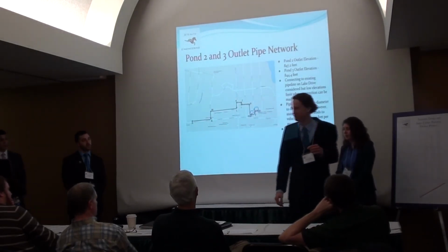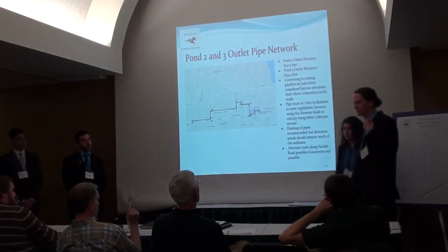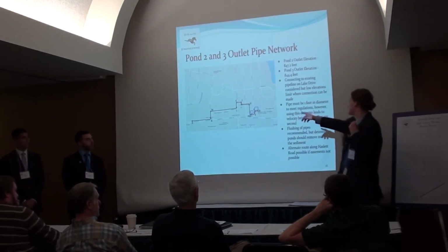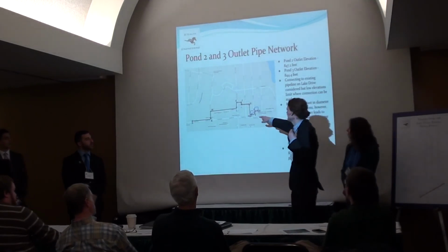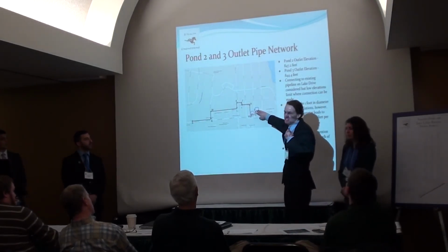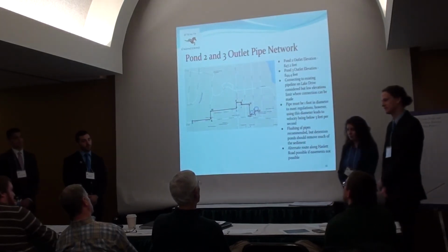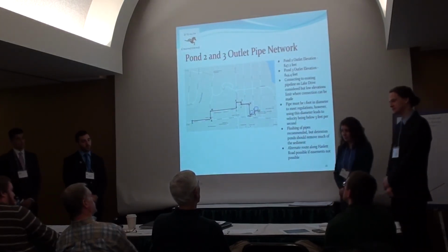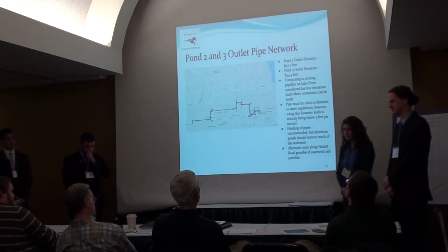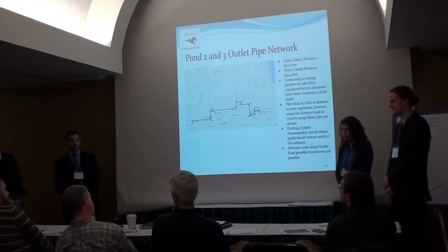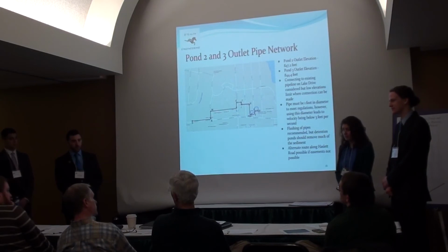What's your invert elevation? Do you know an invert elevation for your outlet pipe? The outlet pipe for this detention pond is at 845 and 847 for that one. So you're below... you're designing your extension area for 100 feet, correct? Yes. So when you're considering your 100-year elevation at your outlet point, you've got an invert that's below that 100-year.